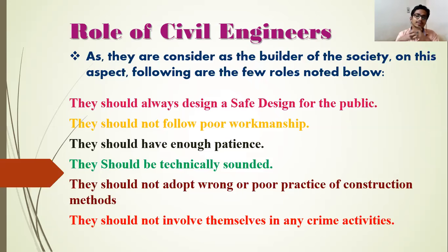I am giving this only as an example. Suppose you are going to use cement. You know what properties a good cement should have, but you have to go for a test. But in most cases, people are not doing tests. They are not giving the time for doing all those things. So ultimately, the structure comes up with a lot of deterioration before its expected life cycle.